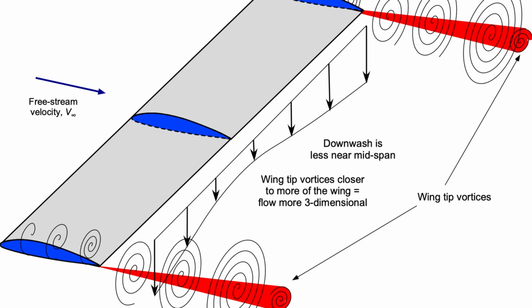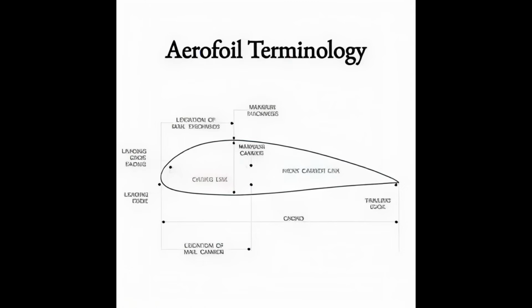This distinction mattered. As aircraft approached high subsonic speeds, airflow normal to the leading edge of the wing accelerated rapidly. Shock waves formed when local airflow exceeded the speed of sound, even though the aircraft itself remained subsonic. These shock waves increased drag dramatically and disrupted lift. Traditional straight wings presented a full free-stream velocity directly to the airfoil, intensifying compressibility effects.